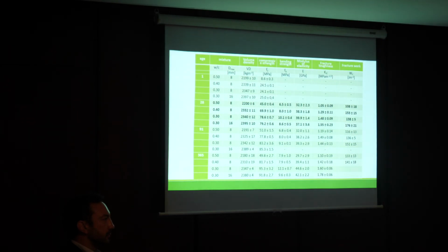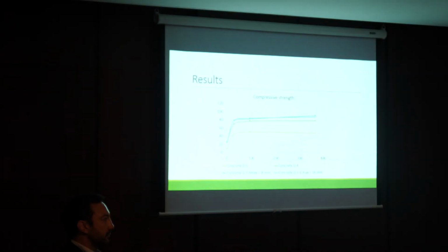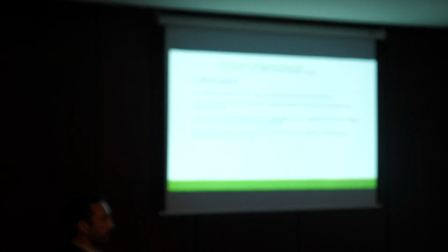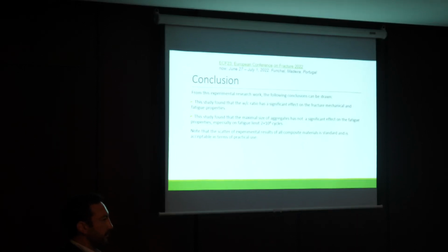It is quite easy: our standard specimens for fatigue are 40 times 40 times 160, and if we want to study fatigue properties, we need at least 5 times the aggregate size for the ligament, according to the recommendation.